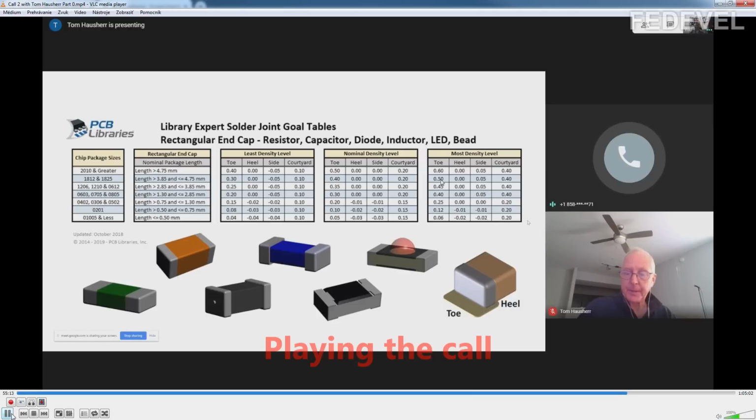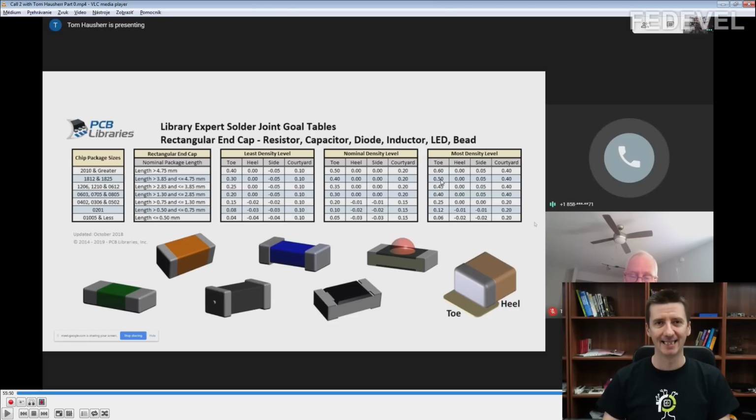Well, I brought this up to IPC way back in 1999 when wave soldering was really big. You know, they wave soldered the whole board, and the consensus from IPC was that wave soldering land patterns and reflow soldering land patterns made no difference. There was no difference in the results. Now some people differ with that. They said that the side should be smaller and the toe should be longer for wave soldering. But IPC has no conclusive proof that the same land pattern can't be used for both soldering processes. The next question, what I really wanted to ask, was about pad shape.